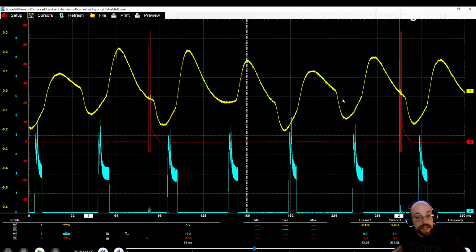And of course, in any scope operations, we always want to make sure that we look at the first destabilization on the left, because everything after the primary destabilization point, which is here, is going to be somewhat skewed. Notice we've got variations in our flow drop levels here. And the primary reason we have these differences in the flow drop levels is because our rail pressure is actually different between these 2 points. So obviously we're going to have our pressure dropping to a different point.